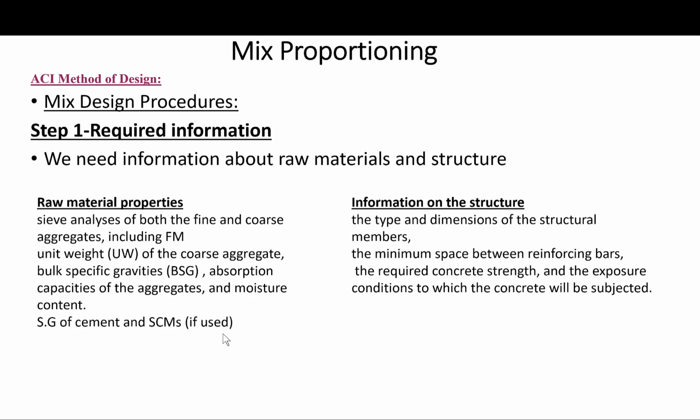Information on the structure includes the type and dimension of the structural members, the minimum spacing between reinforcing bars, the required concrete strength, the exposure conditions to which the concrete will be subjected. All right? You need all this information in order to design a mix. Okay?